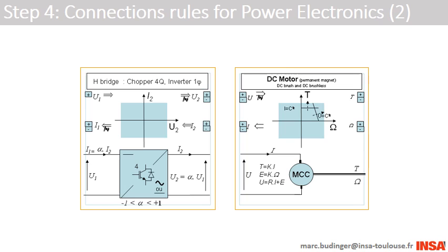On the two examples above, the alternation between current and voltage sources implies that some components, like an inductive motor, will have to be supplied by a voltage source. This voltage source is allowed to rapidly fluctuate around the average value. A converter, such as a chopper, does not change the nature of the source, but can generate fast voltage variation. The inductive nature of the motor filters these disturbances, and the resulting current presents low ripples.